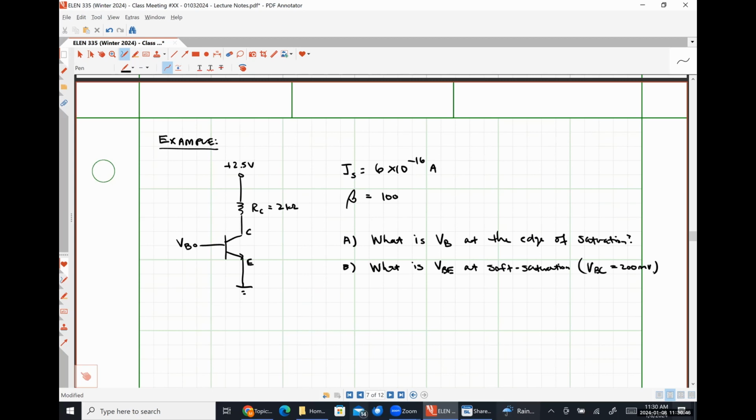So how about we go about solving it without using the large signal model? Because again, I believe it is asinine and useless. So what I'm going to do is I'm effectively just going to write a Kirchhoff's voltage law equation down this right-hand leg. Okay. So effectively, I'm going to say that 2.5 volts is equal to the sum of the voltage drop across the resistor plus VCE, because that's exactly the voltages that I'm going to have going down that